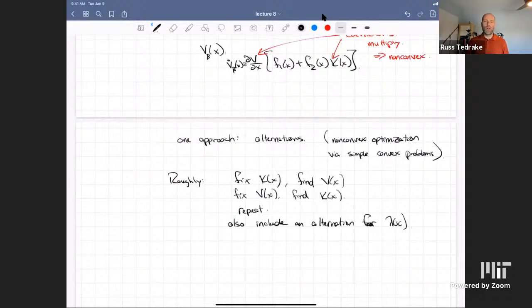Here's an example of something that definitely works, right? If you take the Acrobot at the top, you start with the LQR controller. You can prove a relatively small region of attraction for it. So the linear controller you get from LQR at the top will give you some region of attraction that you can prove with sums of squares.